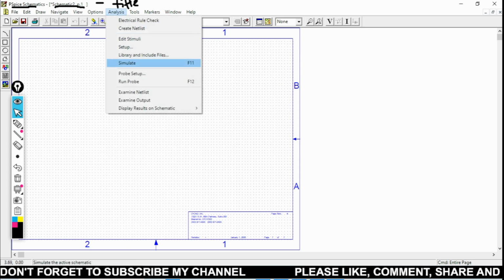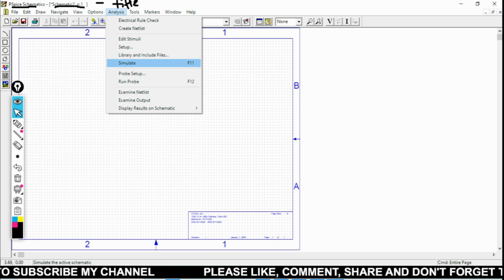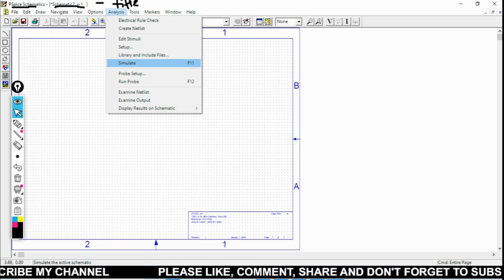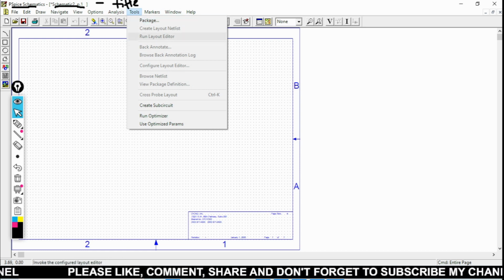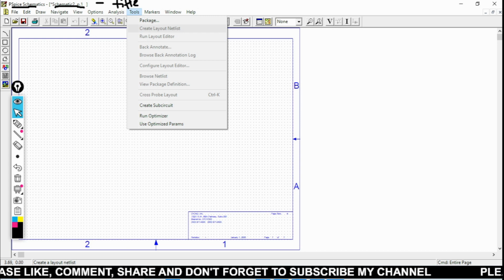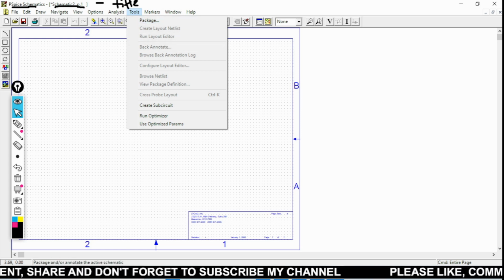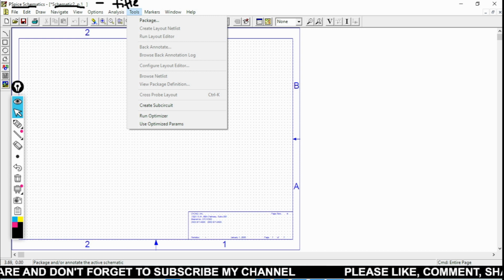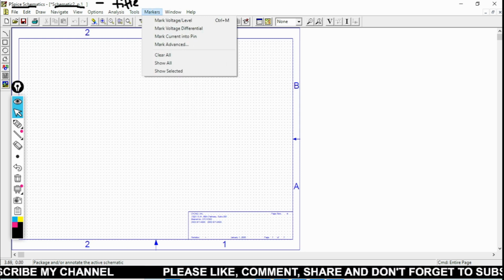Then there is the next part called simulate. F11 is the shortcut for that. If we simulate it, it will show us the simulation. There are also tools where, if we go for PCB designing, we need to create a layout netlist and run the layout editor and so on. For that purpose there is a tool. But we are going to stick to the first one for the simulation purpose only.